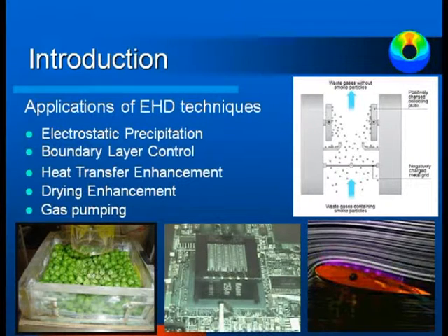Then there is a grounded electrode, where the particles will be deposited, and the clean air can be released. In a power plant, there is a mechanism to shake the electrode and collect the dust. This is the most well-known application of the electrical field.